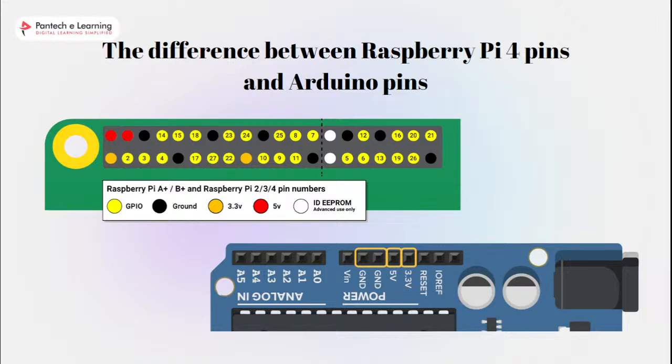There are no pulse width modulation pins on the Raspberry Pi either. Pulse width modulation is quite useful to control components with a non-binary command, right? You can fake a pulse width modulation pin from software, for example with the wiringPi library, but it's clearly not recommended. Arduino is much closer to hardware than Raspberry Pi, and thus there are many native hardware functionalities that you can't get on a Raspberry Pi board.